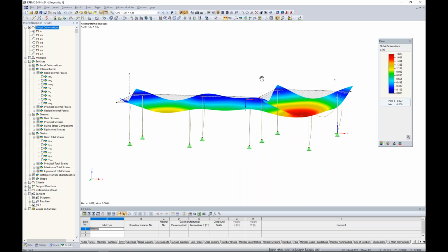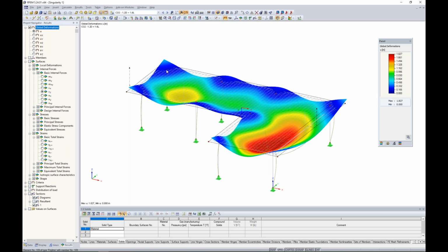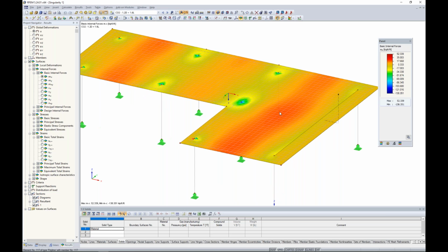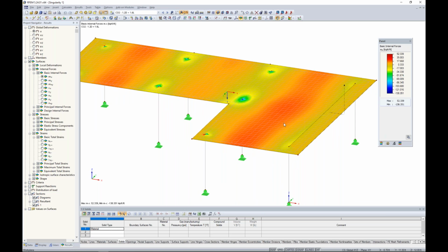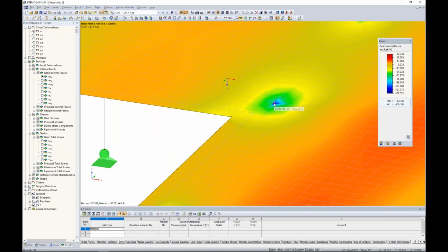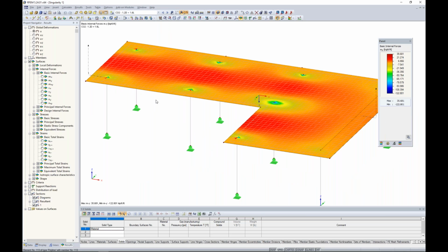Well, okay, the initial deflection, nothing too strange here. But let's take a look at the internal forces for our slab element. And so we'll turn this on and we'll take a look at MX. Well, initially looking, MX looks okay. Obviously we're seeing some positive bending moment in between these column supports. But then there's the case here over the columns where we're seeing extremely high negative bending moments. And of course, there will still be some negative bending, but these look to be pretty high at these locations. MY, same concept, positive bending in between where these columns are spanning, but then very high negative bending moments where it frames into these single 1D member elements.